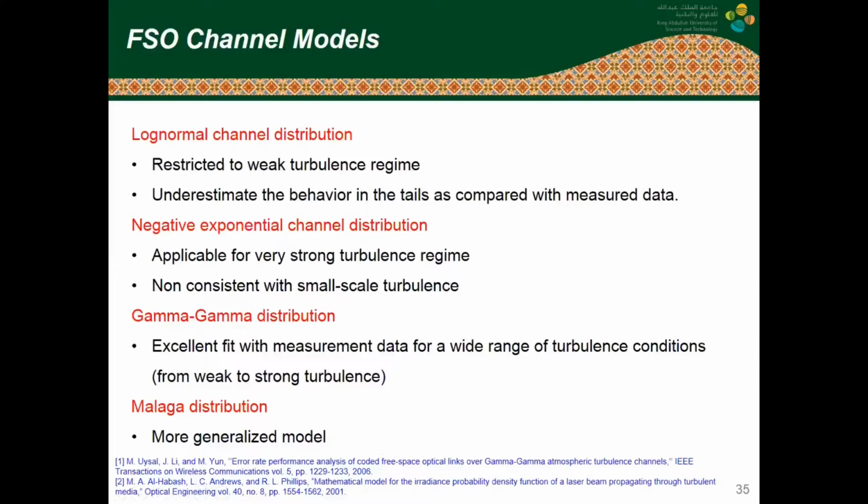And that's acceptable if we really have to deal with a super strong turbulence regime. This is not always the case. So as a way to bridge these two extremes between weak turbulence and very strong turbulence, one can use a very handy gamma-gamma distribution, which spans the range from essentially an exponential distribution all the way to some kind of log normal or gamma type model.